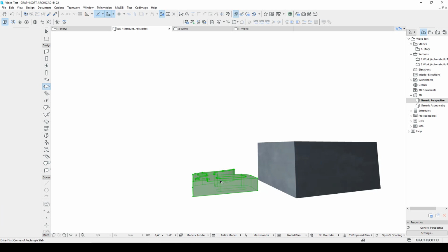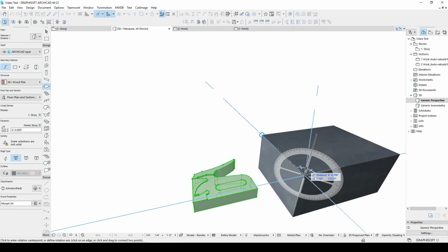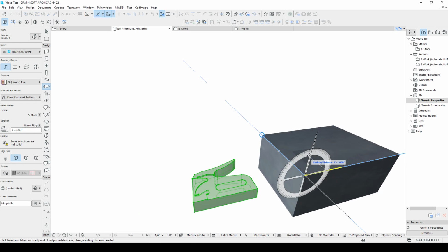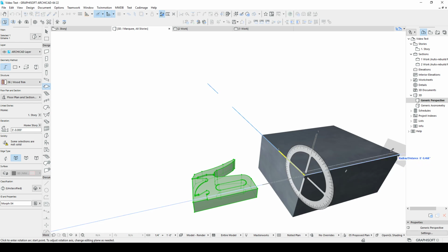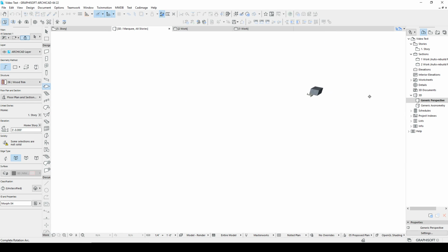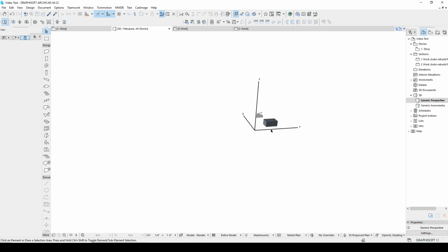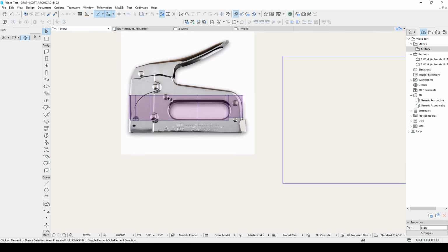to rotate elements properly. So if I select that morph and hit F6, F6 is my rotate. And now if I click and hold and not release until I've got the orientation of my rotation established. So there's my second click. Actually, that's the wrong way. So I'm going to hit F6. I want to rotate about this. And I'm just going to go 90 degrees. And that makes the stapler a little easier to maneuver. But again, we lost our tracing ability. But there it is.